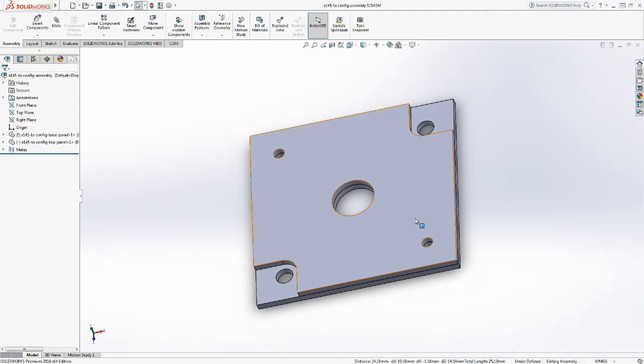What having the assembly allows us to do is see, whenever we make a change to a panel, how that's going to affect the overall look of the panel. So that's really handy if we're trying to make some kind of edits somewhere and we need to verify that the holes align or verify that something else aligns properly. And where this is going to become important is here in just a moment. We're going to go back and edit that base panel a little bit because we're going to add some holes for an LED that's going to basically mount to that base panel so that we can get the backlighting that we're going to require. Let's go back to our top panel.